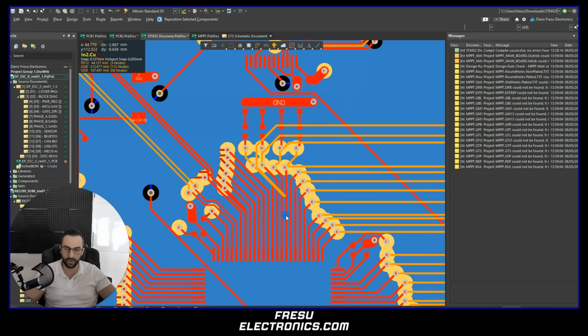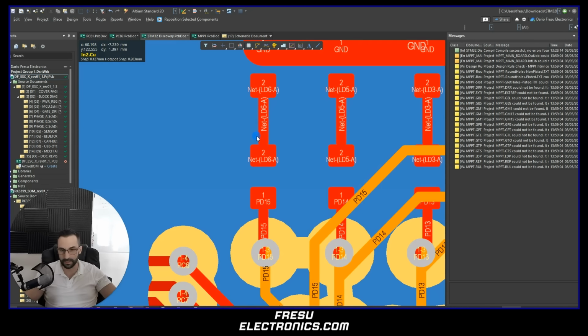And this is going to create a problem when you have either a microcontroller or a processor or an FPGA, which requires some instantaneous sharp energy. So when it's requiring this energy in peaks, then this is going to create a problem, because then you will have these fast switching signals which see the impedance in here.